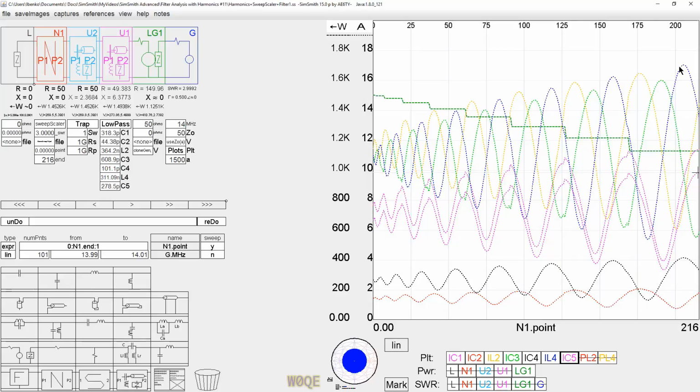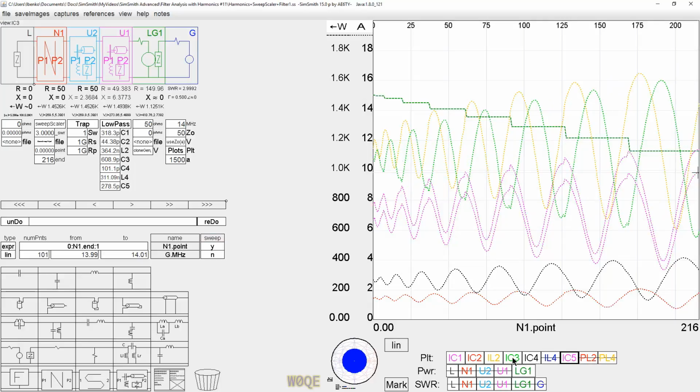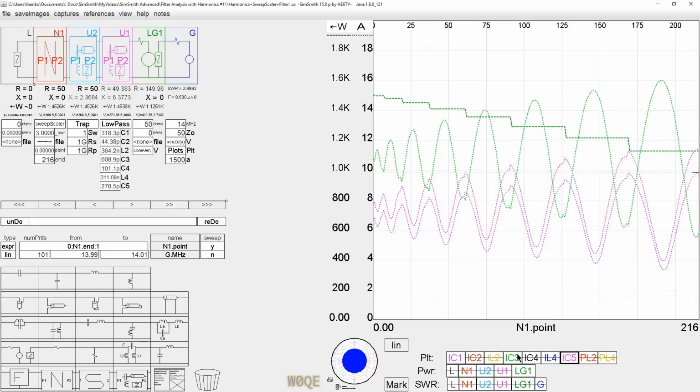And in the cases I've been able to look at, people size the components all equally a lot of times. Every one of the capacitors in this filter would be the same size, where it becomes pretty obvious. I'm not plotting power right now in the capacitors, but if I just look at the current in the three big capacitors, which are capacitors 1, 3, and 5, I see that clearly this capacitor, which is C3, has 16 amps of current in it, where these other ones have 11.